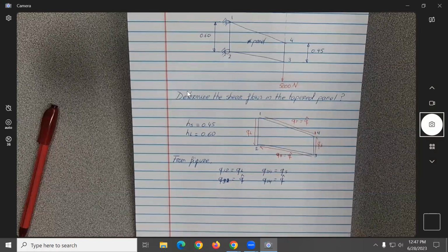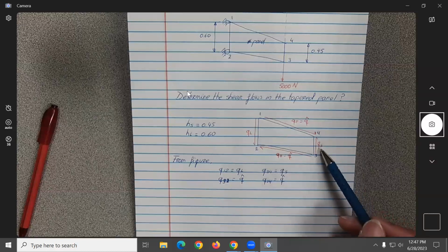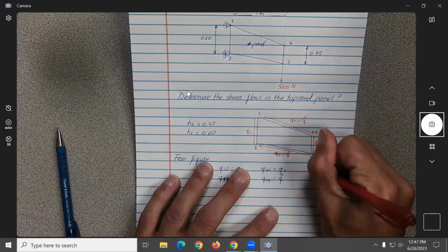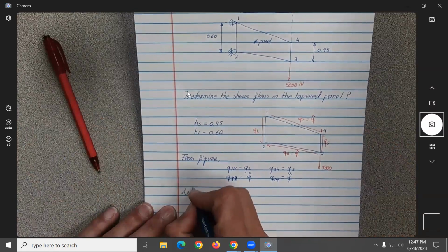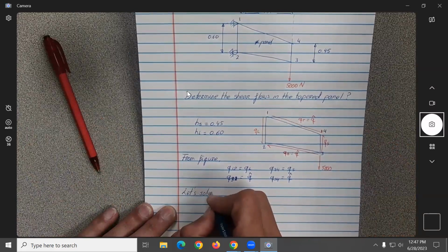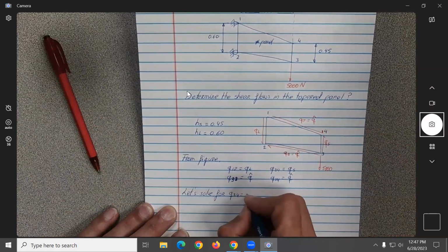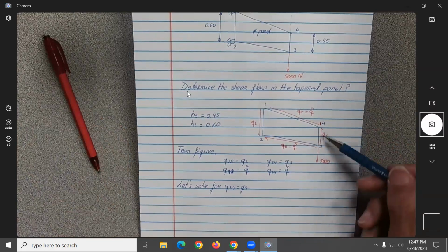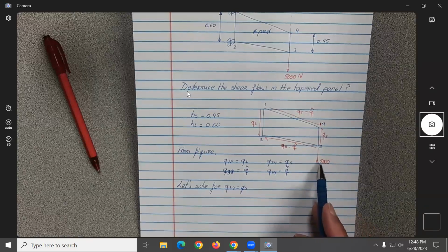Okay, so in order to find all these ones, Q12, Q23, Q14, what is the only one we need to solve for? Q short, no? What can we do in order to solve for Q short? For Q34 equal Q short, what is the value of the force in that member? $1,000.